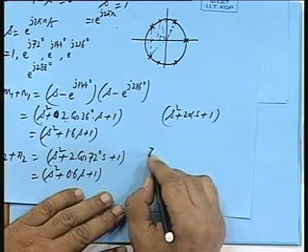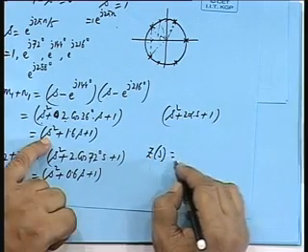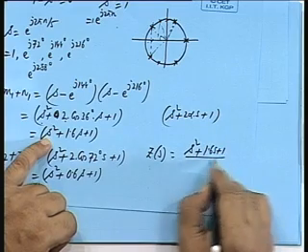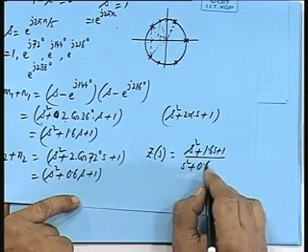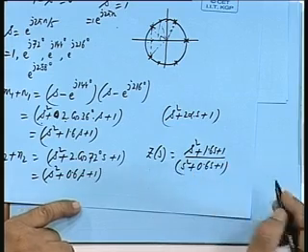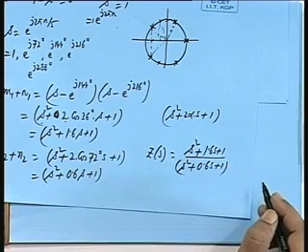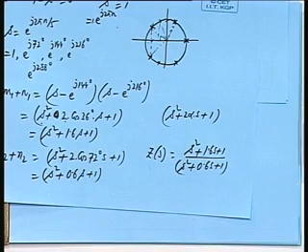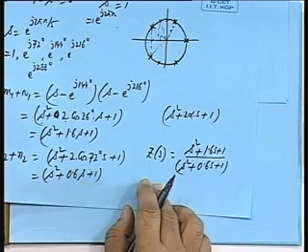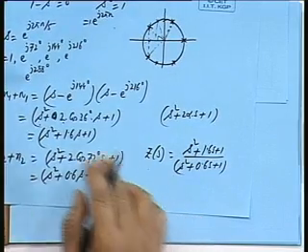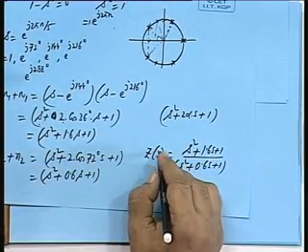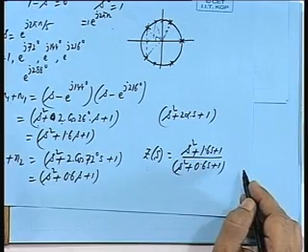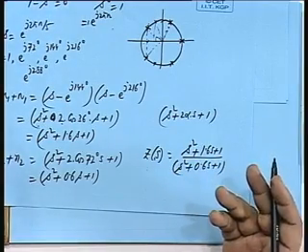So, Zs is, this one will be the numerator, s squared plus 1.6 s plus 1 divided by s squared plus 0.6 s plus 1, approximately this will be the function. Is that okay? So, we have seen how to calculate the function Zs from the phase. Now, from here you can calculate the magnitude. Once you know the actual Zs, you can calculate the magnitude.